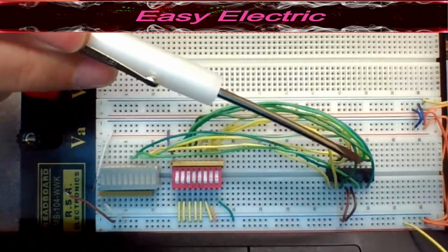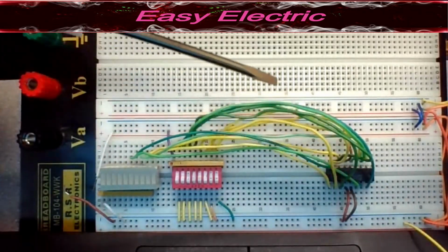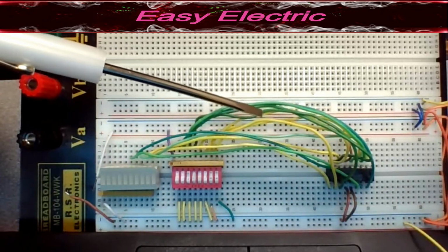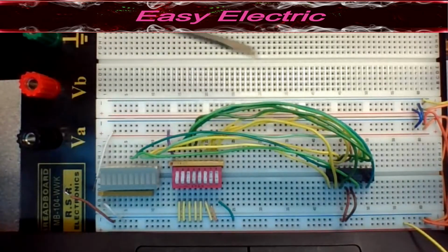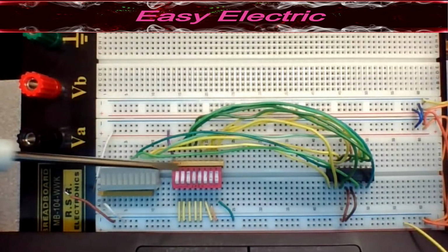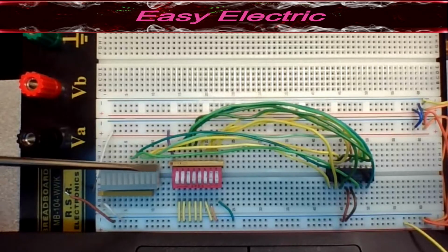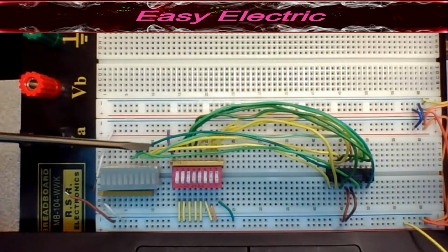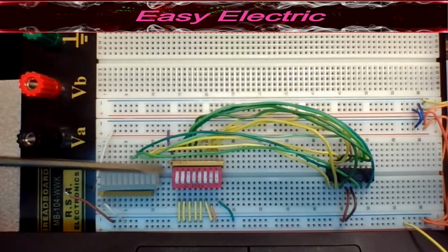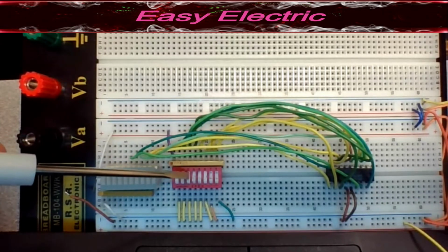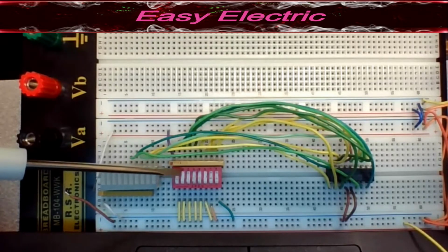So here I have one 7483 and we make the circuit exactly based on what we saw in the simulation. Here this is my test bench, which I explained in our first video. If you don't know what this test bench is, please check our previous video where we explain how you could make that. Here I have 4 switches which let me give B. The 4 switches on my right are B4, B3, B2 and B1. We start with 1, 2, 4. This one is the highest value and this one is the lowest value.